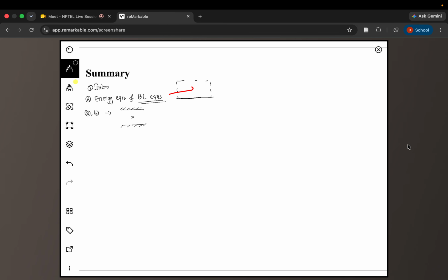So both of these are with respect to forced convection, and then we'll again follow the same strategy for natural convection flows. I think this is up to week 5, and this will be week 7, 8 or something. I'm not sure about the week numbers, but then we will move on to natural convection. Like I said, in forced convection problems, the main driver is the forces that are happening at the boundary. In natural convection, we'll have a buoyancy force, that is a body force, which will be acting throughout the volume of our interest. Again, here we will do the same cases, external and internal.